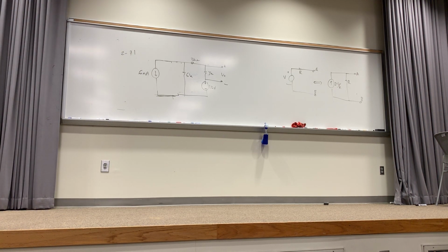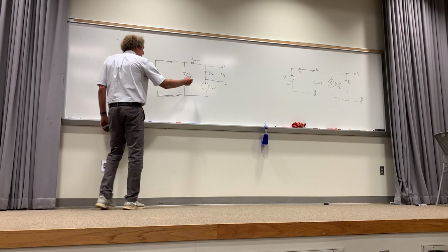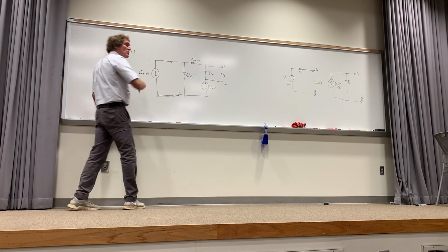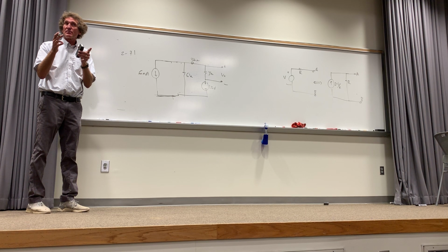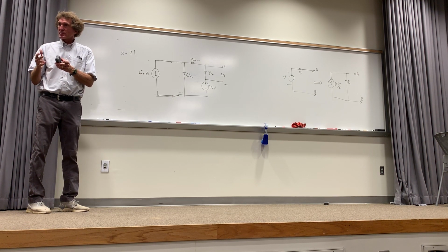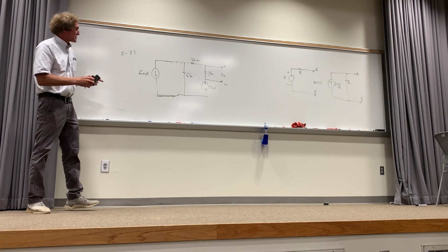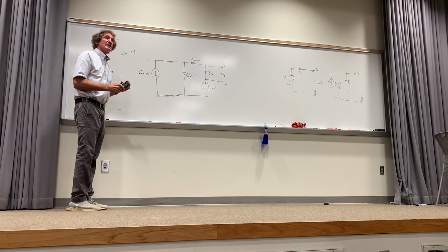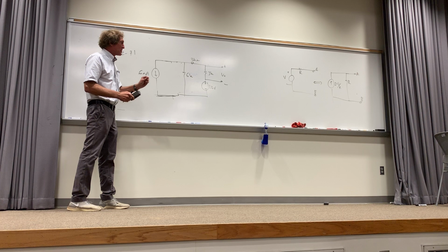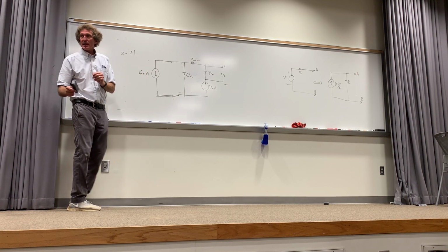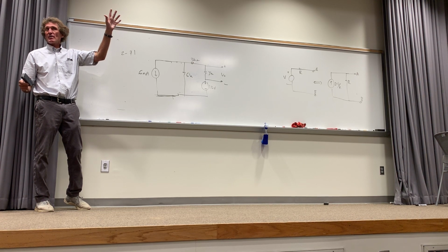Now with source transforms, you go from a series resistance, series voltage, to a parallel resistance, parallel current source, and then back, and vice versa, back and forth. So now I take this here, and I make it a voltage source in series with 6K. You see how I'm absorbing one element. I'm reducing the number of elements in the circuit by one every time I do a source transform. I absorb elements. You see this, everyone? I'm combining things. So for this one, I'm going to get a voltage with a positive polarity downward of 6 milliamps times 6K, or 36 volts, right? And it's going to be in series with 6K. Can everybody see that and understand what I'm doing? Give me a show of hands if you do. I want to make sure that nobody's puzzled.